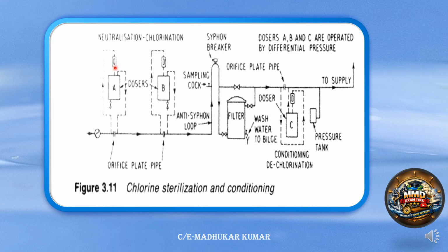The water is passing through A, and here we are neutralizing it. We have the calcium and magnesium compounds, and here the water is going to be added to it. So neutralizing the acid, absorbing CO2, and the hardness is there, improving the taste. All these things are happening in this doser. After that, the water is coming out and connecting with the main stream.